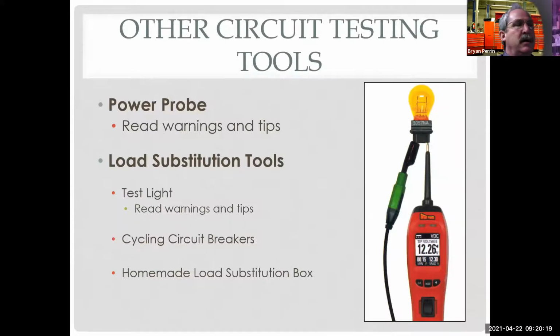And it's just a great tool, and it has a built-in 20-amp circuit breaker. So if you hook up to a motor wrong, or you hook up to something wrong, and you try to power it up and it pops the circuit breaker, you go, whoa, I just popped the circuit breaker. What did I do wrong? You can look at it, push the button in, didn't cost you anything, and redo it. So this is great for bench testing stuff.